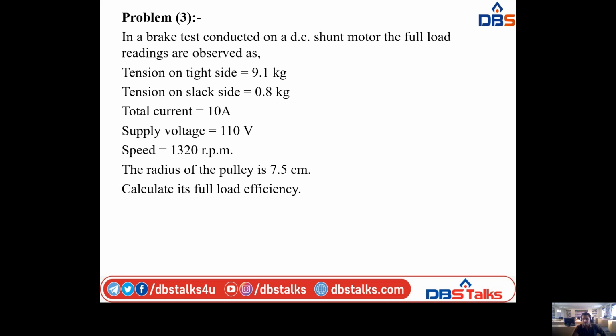Okay, next coming to the efficiency of motor and generator. Firstly, we have to calculate the efficiency of the motor. If we want to calculate the efficiency of the motor, we have to know the output power and input power. So firstly, we have to calculate the motor input power, that is equal to V into I. For the motor, they gave the supply voltage 230 into current, they already gave 37.85. This is the armature current value, 37.85. And finally, we have the motor input power, that is 8705.5 watts.